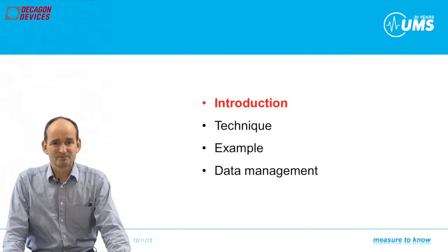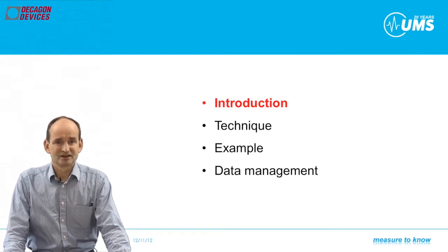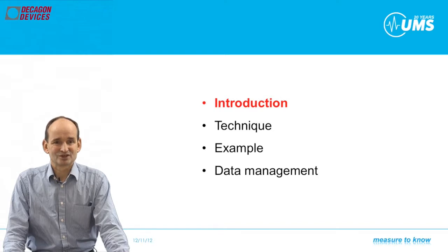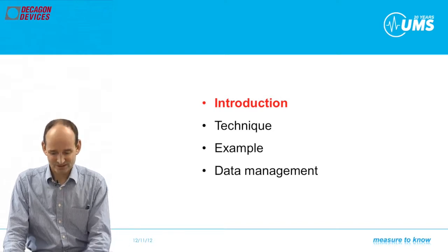Lysimeters are not only monitoring instruments, they actively control the water situation and therefore need a critical eye on what happens in the field and at the lysimeter. A fifth chapter could have been the maintenance, which includes an at least weekly data check and at least 2 site visits a year to check the system and the local situation.